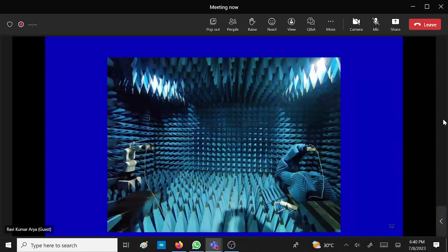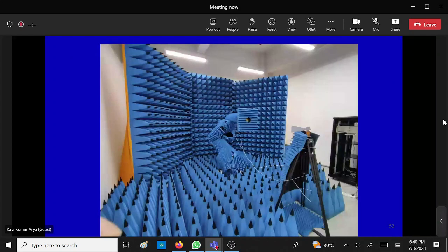This is inside our chamber. So typically this near field chamber is something like this, that you have the radiating element, then we have the absorber on the other side. Then we have the robotic arm here, and we can move the direction. Basically, near field, you measure the field near to the antenna, and then from near field to far field transformation, you can calculate how the far field is. So we have two anechoic near field chambers.